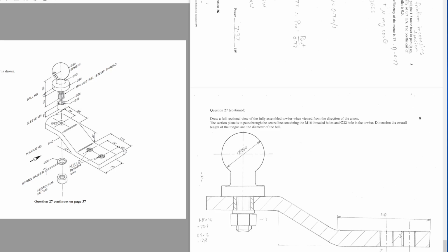Now, I would make a mark for that. If it was me, I would have a mark for that. I don't have many spacings, but I have enough that I can demonstrate. I always like to do my hatching really wide because I think it saves a whole lot of time. But you can see that I've done enough to show that I have hatched it to show that it's threaded and that there's nothing in the thread. Then you have to include this line here because you should be able to see that line on the outside, and I don't know why they didn't include that.